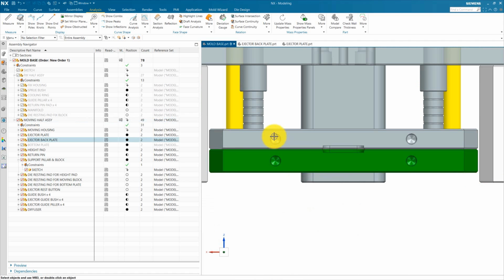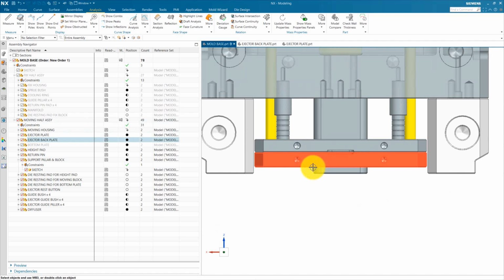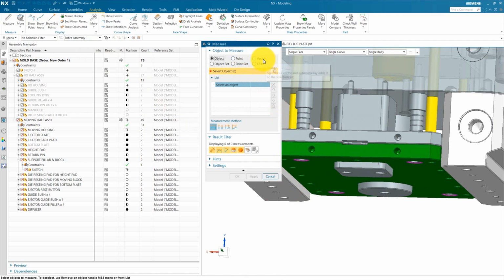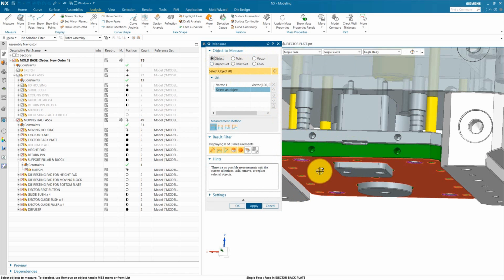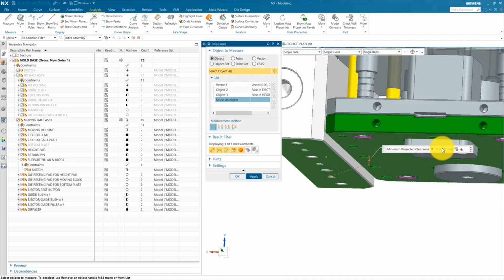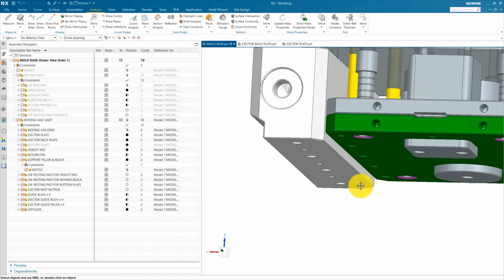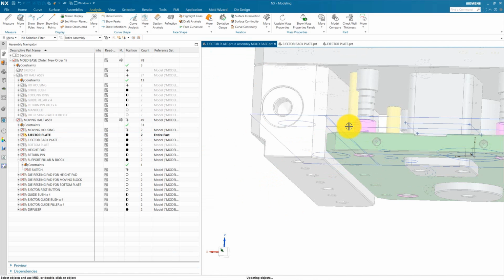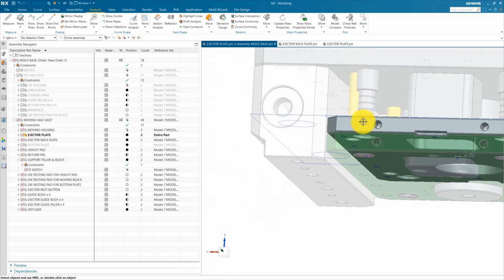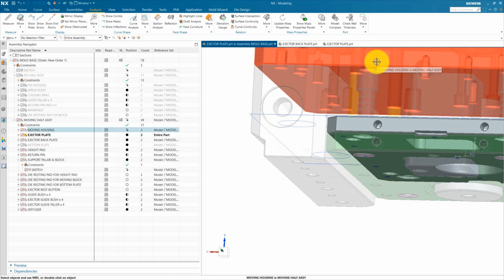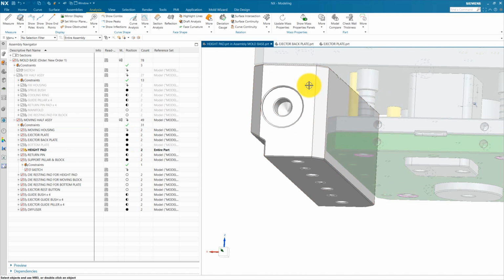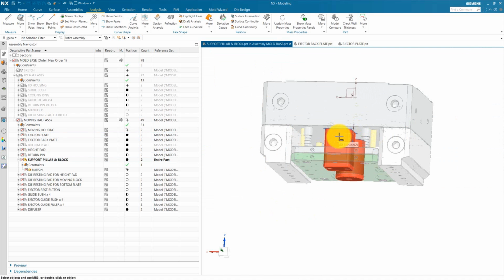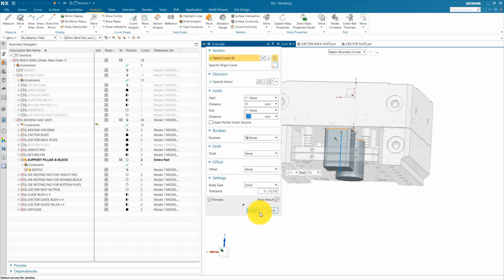76 plus 40 plus this ejector plate thickness plus our ejector back plate thickness plus the rest button thickness, which is 15 mm. From here to here we need 15, which is already updated. So 15 plus this height, which is 35, plus this height, which is 30, plus ejection height, which is 76, plus this height, which is 40. That all is equal to this height, 175, which is our pad height, and the support pillar height is also equal to our pad height, which is 175.